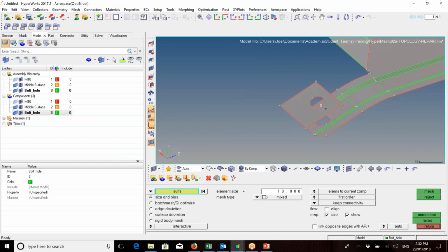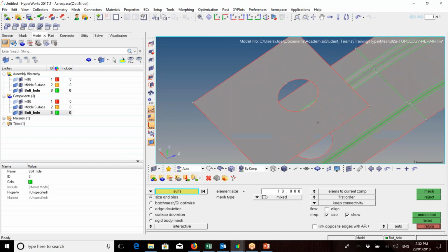We can see that little square there. We've got this little legend down here telling you the distance. This is units. It's always a good thing to remember that HyperMesh does not have an actual unit system, so you need to be aware what units the model is in when you import. This just tells you 1 unit length. This could be 4 meters, could be 4 millimeters. For this model, it's millimeters, but you need to be aware of what units you've built it in.